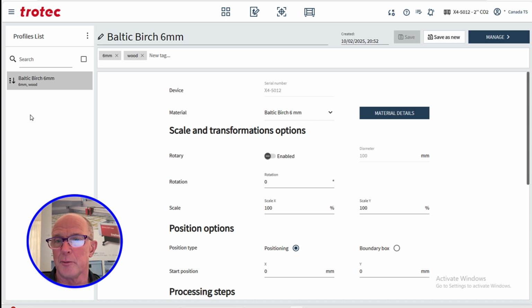If you're bringing in a normal logo or a normal job from Corel or Illustrator or AutoCAD, you can easily do that in the Manage screen just with the normal import function. However, in profiles, right now only PDF is supported. I've been told that the other formats that we're importing into Manage now will also work in the 2.11 update.